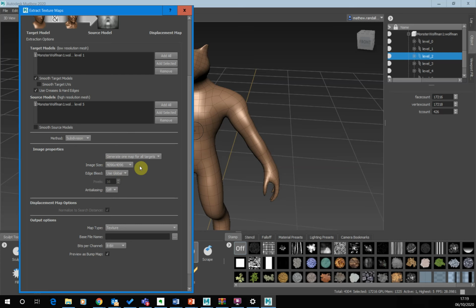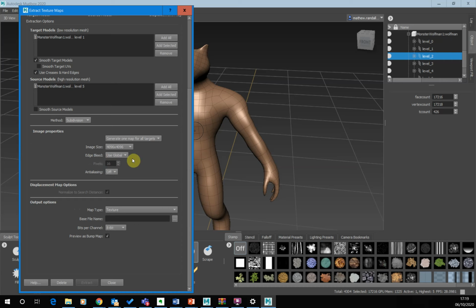Brilliant. Then, to support a displacement map, we need a high color resolution. Okay, so we need lots of bits per channel. A standard JPEG type color resolution isn't enough. To have a really detailed displacement map, we want to go for a 32-bit floating point image. It's a large image, but we need that detail. Okay, so we've got that.